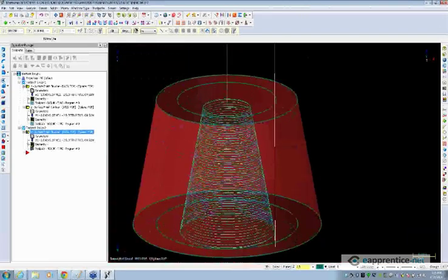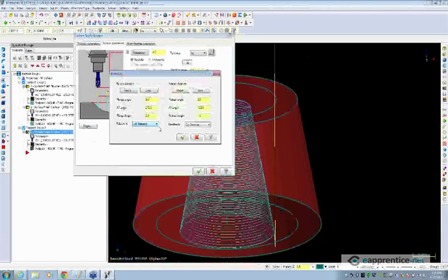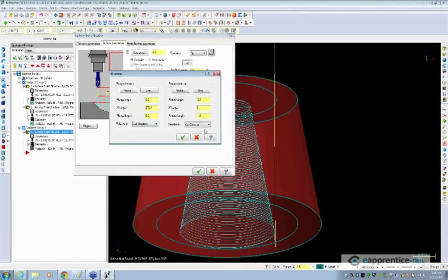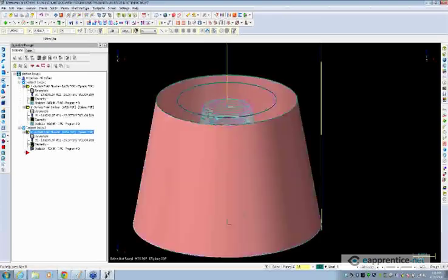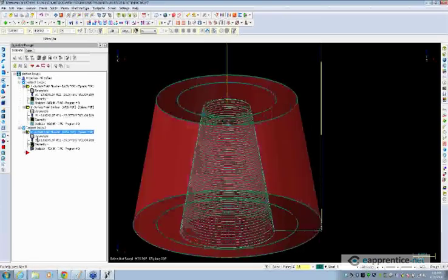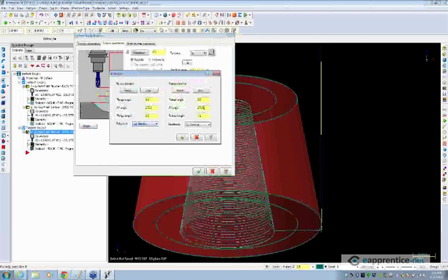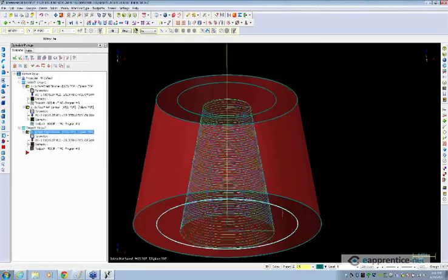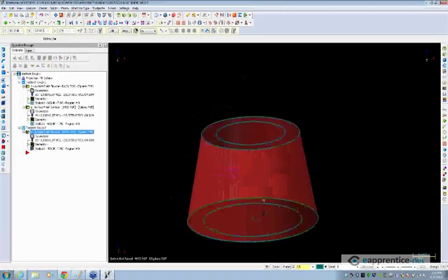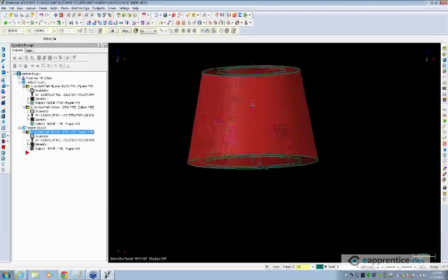Now we just need to fix this exit. So I'll do the same thing here. We've got 180, so I'm either going to need 90 or 270. 270 might be out to the right. Let's check that. Yeah, so we're going to need 90. So here's the directions going out to the right. That's the incorrect way. So we'll change that to 90. Now again, this is relative to the cut direction. So now we've got this nice entry motion that's a lead in.